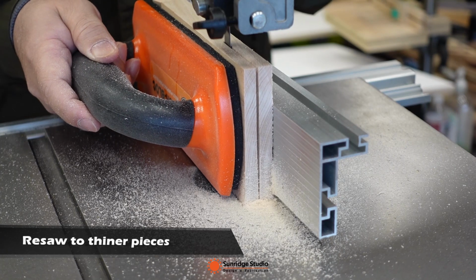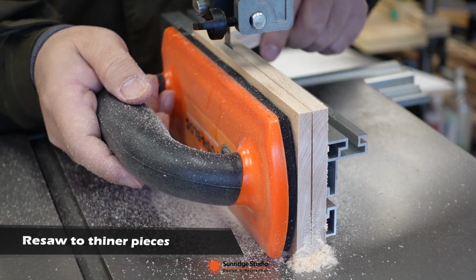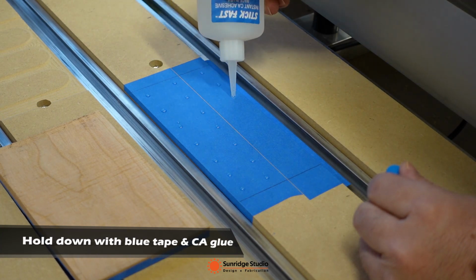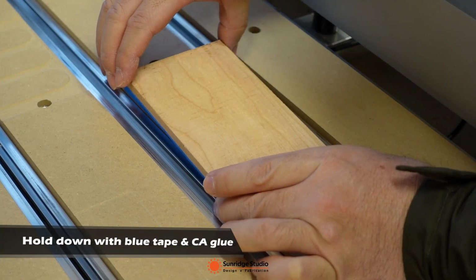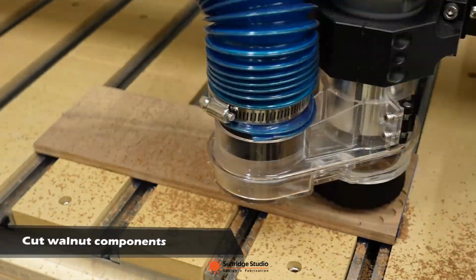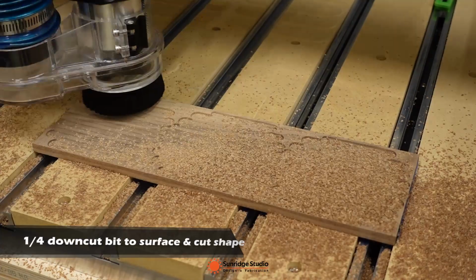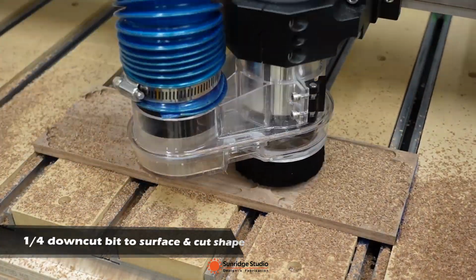For the CNC toolpath, I first used a 1/4 inch downcut bit to surface the pieces and remove bandsaw marks. Then I cut most of the shape also with this bit. Then I used a 90° V bit to chamfer the top edges. For the walnut pieces, I also used a 1/8 inch flat end mill to contour the finished path for the inlay edges, as the corners cut by the 1/4 inch bit are too rounded.